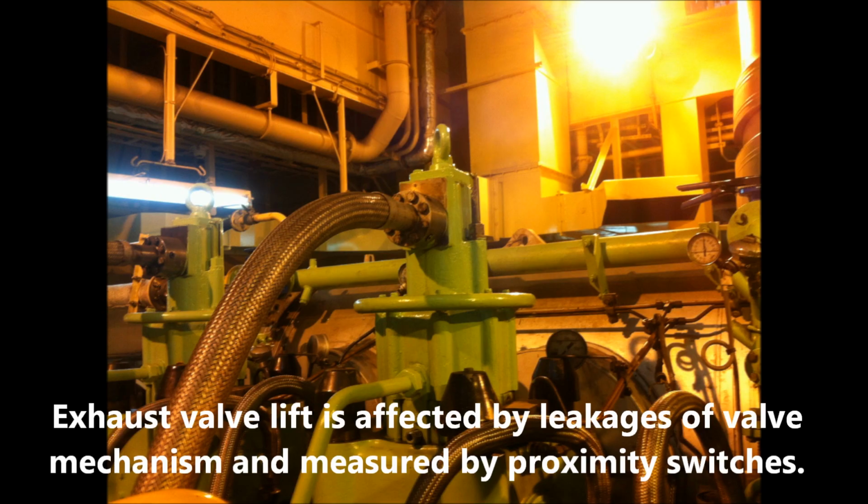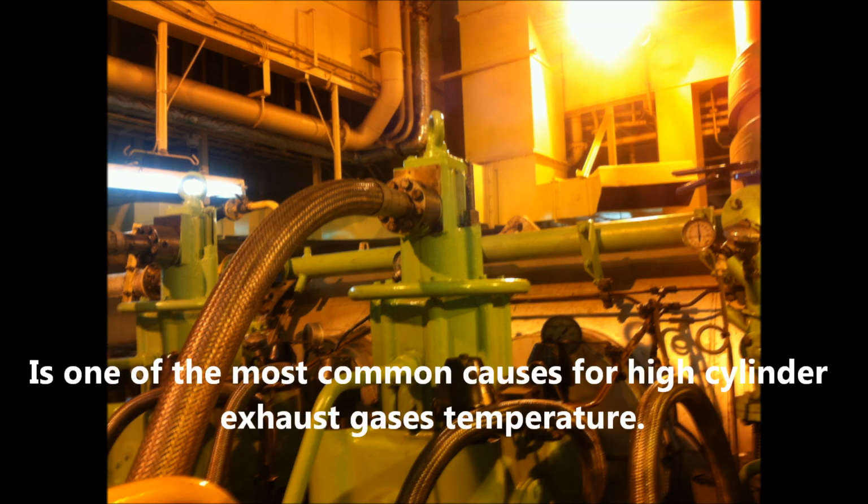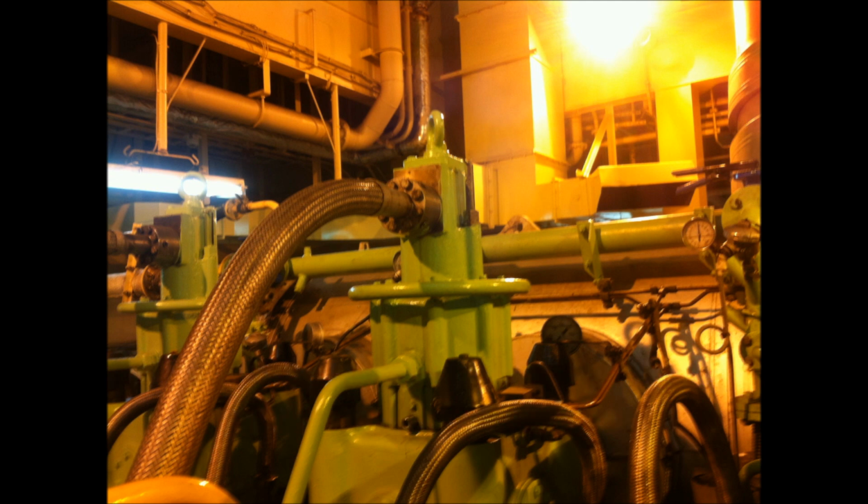Exhaust valve lift is affected by leakages of the valve mechanism and is measured by proximity switches. It is one of the most common causes of high cylinder exhaust gas temperature.